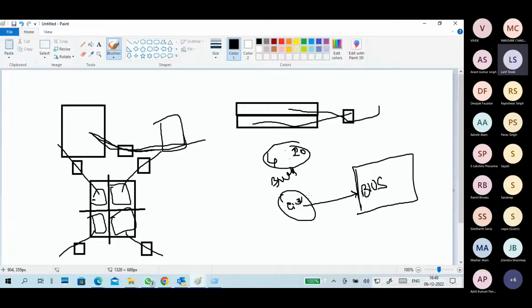Okay, if in case you remove this battery, what will happen? If you remove this battery, there is no power supply to your CMOS chipset, and the date and time, your settings, and the passwords will go back to the factory default. Factory default means the settings your motherboard had by default when you purchased it. The default settings will be loaded, and your changed settings won't be there. So that's why we use this lithium battery.